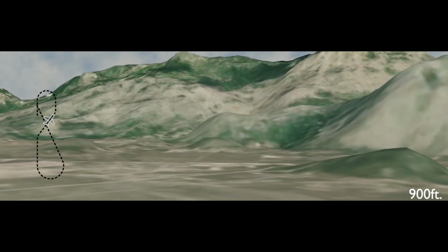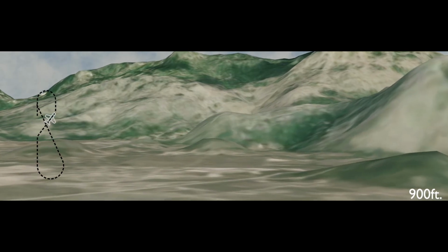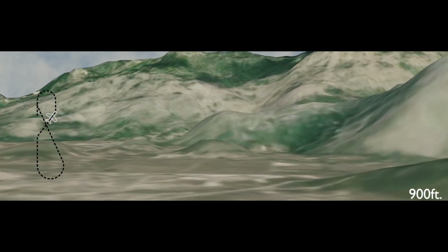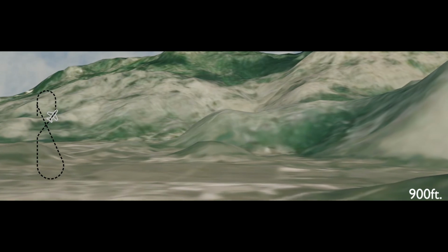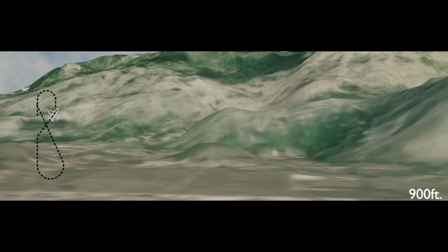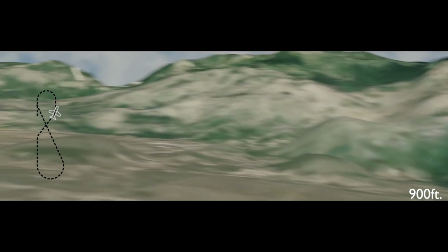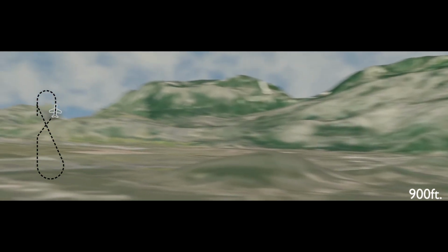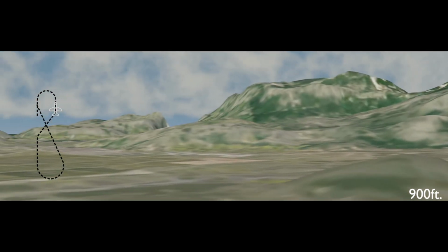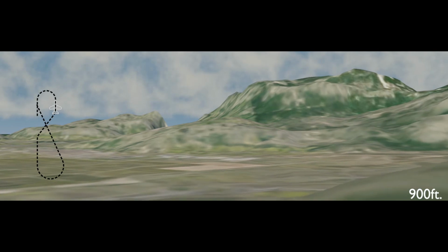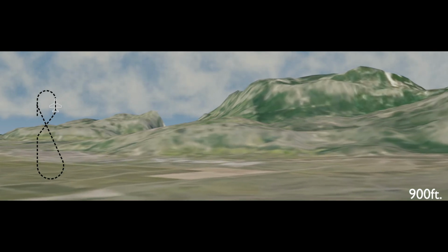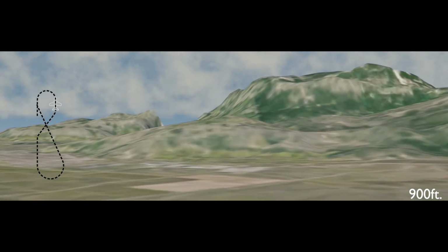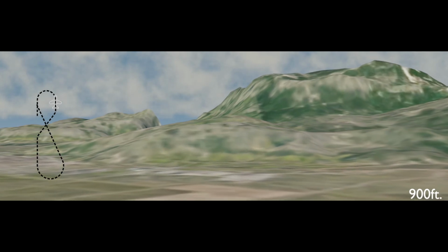There's high ground ahead of the aircraft, so it's important to follow the prescribed track. The cue for the downwind turn is the 112 radial from Podgorica VOR. We're now downwind following the prescribed track of 360 magnetic until we cross the 074 radial from Podgorica VOR.